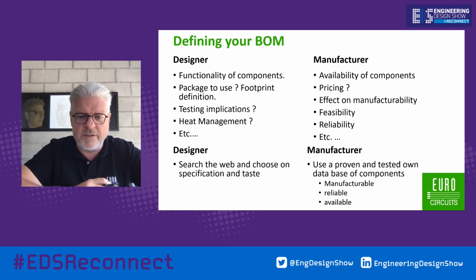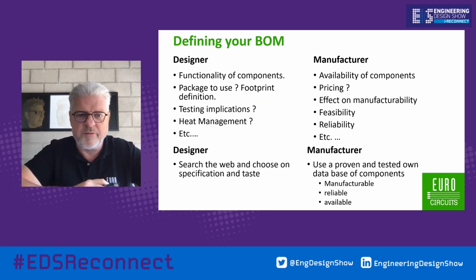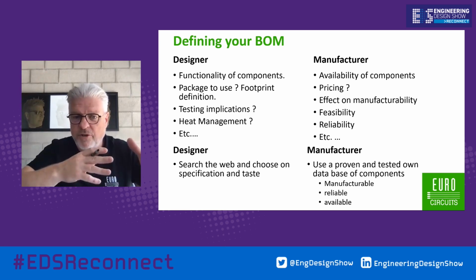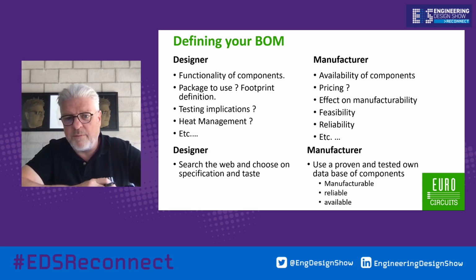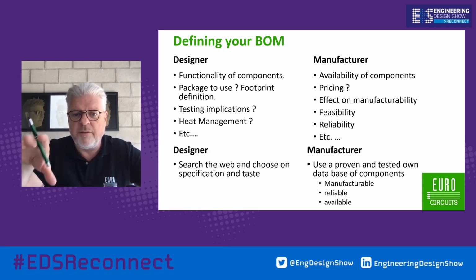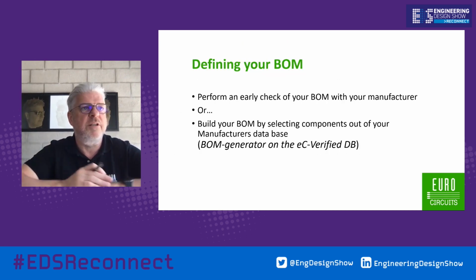But there is a little difference in the way we and you look at the bill of material. As a designer, you look more in terms of electronic functionality, and you use tools like the web and so on. On the manufacturing side, we look at what is the availability of this, what is the effect of these components on manufacturability, the feasibility, the reliability, and are these proven and tested components in our database? So already there, our vision on things is a little bit different.